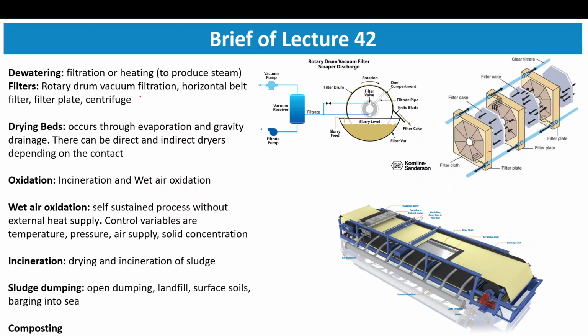Now, this was all about filtration. Another way of concentrating the sludge, or recovering the water content in the sludge, is by heat treatment, because water will be converted into vapors, right? So evaporation is one such way of doing that, and there can be dryers.